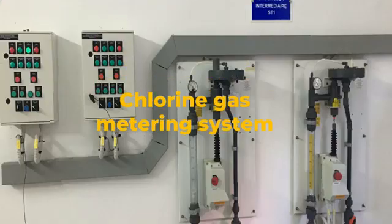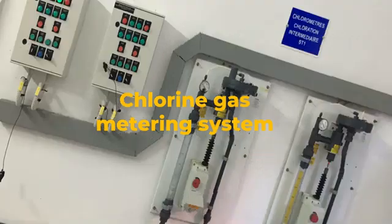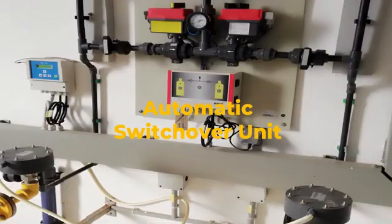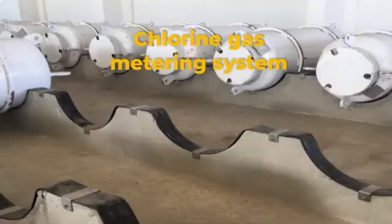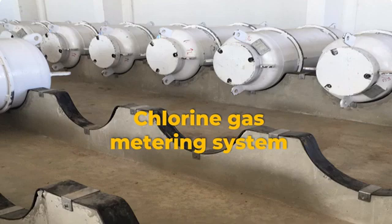Here you can see some pictures of an installation of the chlorine gas dosing system in a water treatment plant. As you can see, different types of equipment are used for typical chlorine gas systems. For large-scale systems, additional components such as evaporators, pressure-reducing valves, pressure switchovers, metering systems and corresponding room equipment are used.